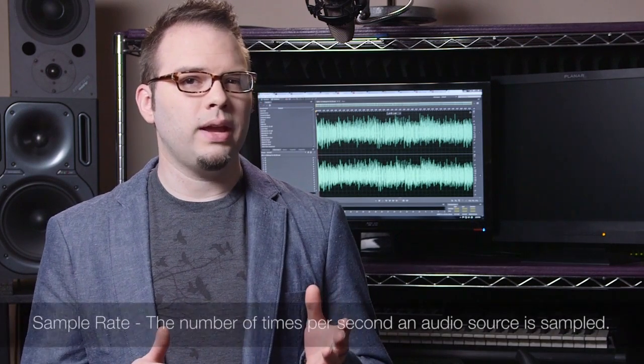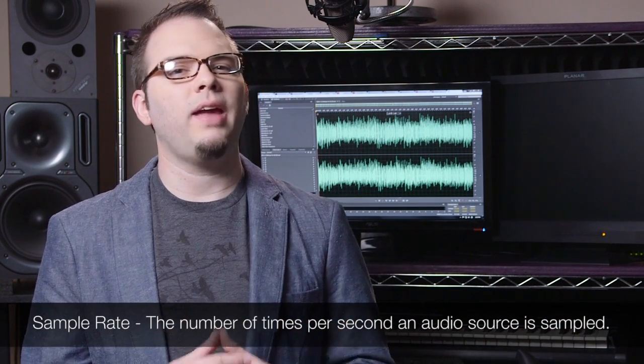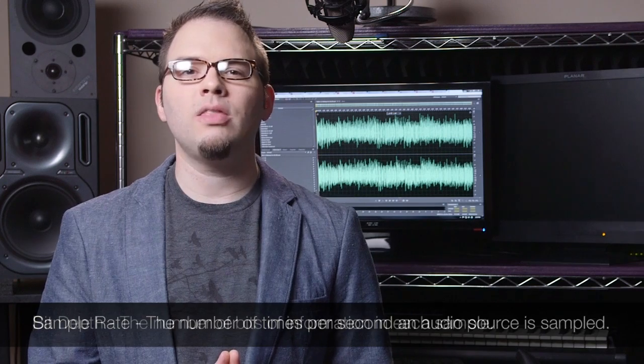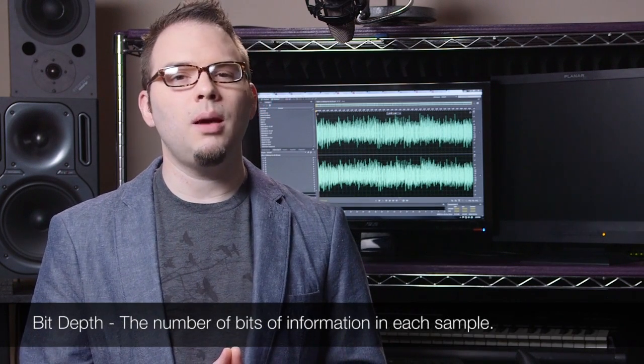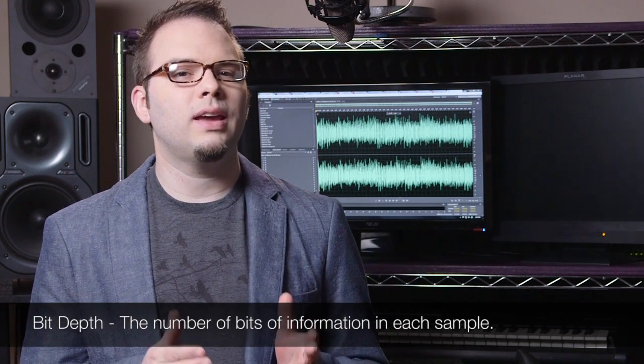All of that sounds a little bit complex, but once you see it in action, you will find that it's pretty straightforward. When the analog to digital conversion happens, there are two properties that determine the data stream's fidelity compared to the original analog signal. The sample rate, which is the number of times per second that samples are taken, and the bit depth, which determines the number of possible digital values that can be used to represent each sample. Let's talk about sample rates first.